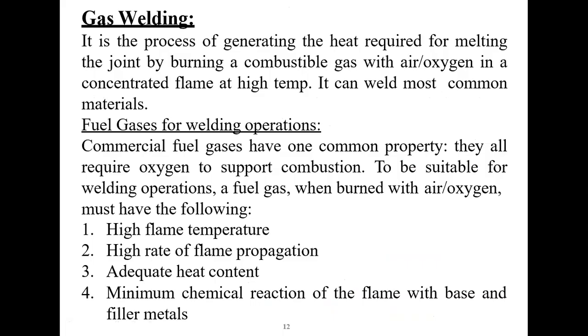So I'm going to my first topic, that is gas welding. In gas welding, we mainly use two gases: one is oxygen and another is acetylene. Here the oxygen supports the fuel gas. Commercial fuel gases have one common property: they all require oxygen to support combustion to be suitable for welding operations.